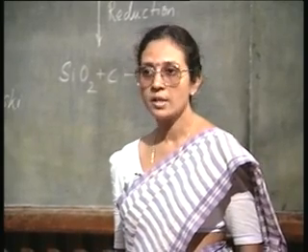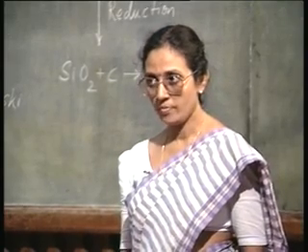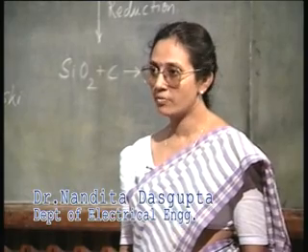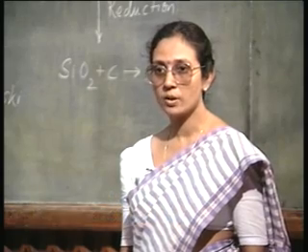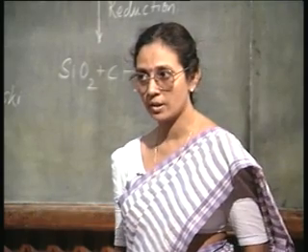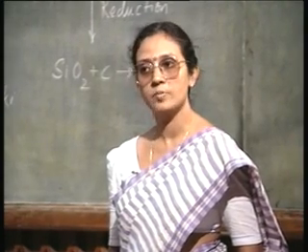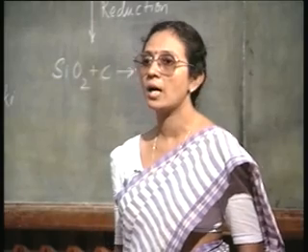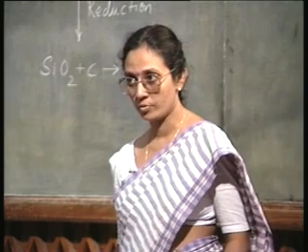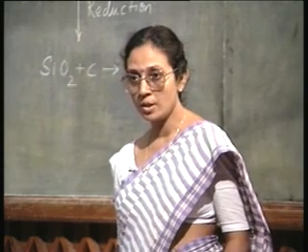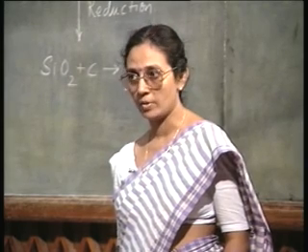So, the Czochralski growth of crystal is obviously more important, but we will discuss briefly the Bridgman technique also, and then we will see what are the problems associated with the Bridgman technique, and then go over to the Czochralski technique, see how these problems are eliminated, and then we will see how the Czochralski grown crystal can be further improved, so as to meet the stringent requirements of the integrated circuit fabrication.